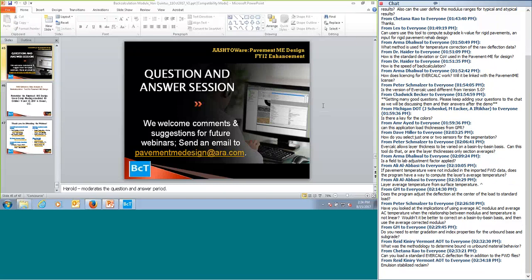It also gives direction on whether that unbound, let's say for a soil cement or a base stabilized material using either an emulsion or a Portland cement, depends on the amount of binder or additive that was used, on whether it would be simulated as a high quality aggregate base or some other type of material.